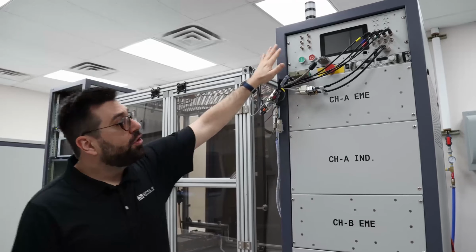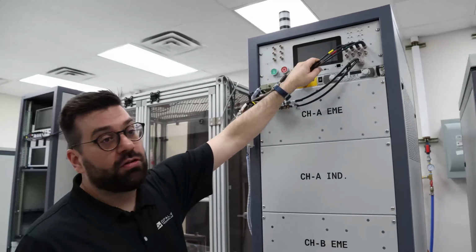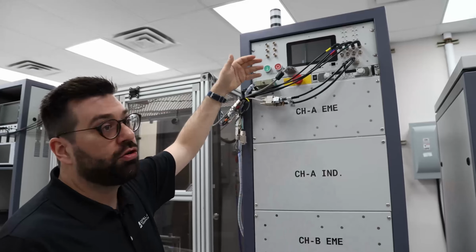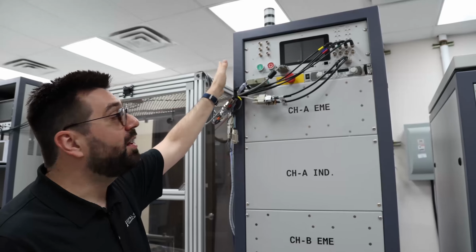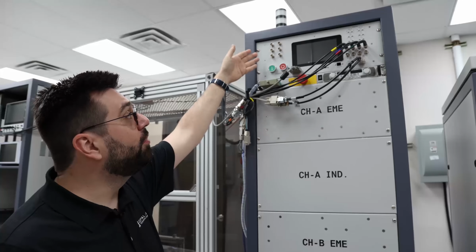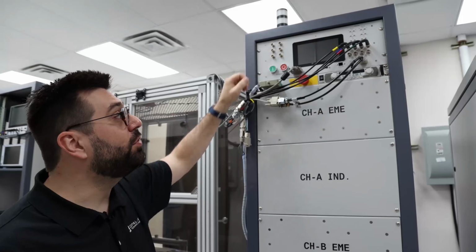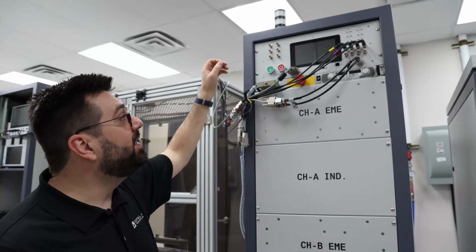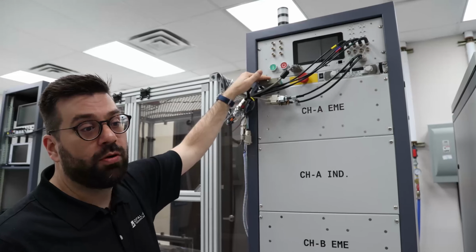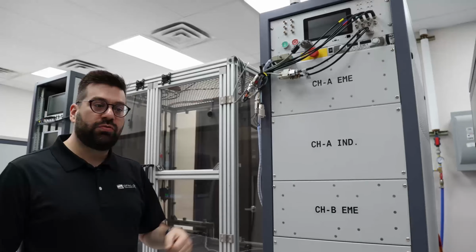What you have here, you have the control for the whole bench that the DNV provides. You have probes here for measuring your voltage or current coming from the equipment to a scope. You have all the encoder, resolver, and low-level signals for connecting your inverters, and we have the connection to OPAL-RT systems. Now let's go to the back to see the connection to the inverters.